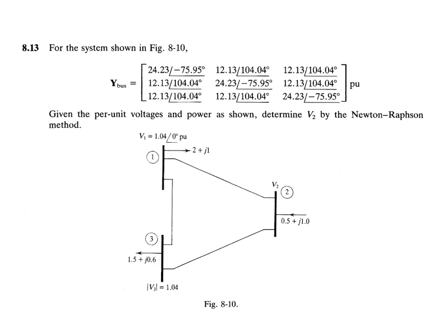In the past, our Y bus was just simply equal to j times a bunch of B's, right? This one has a G plus jB in it, doesn't it? So remember when you've written your equations in the past, you've always said G was equal to 0. That is not the case this time. So you can't throw those away.